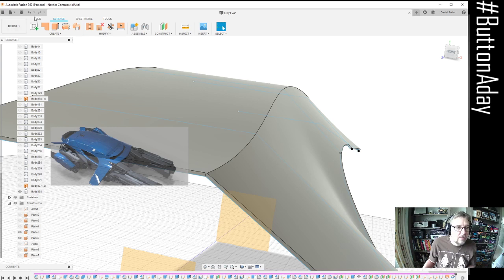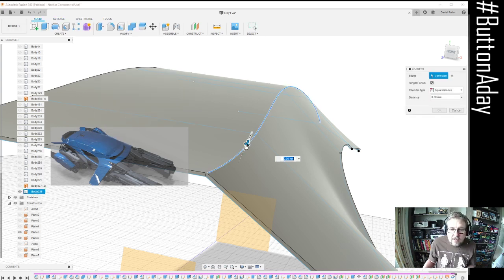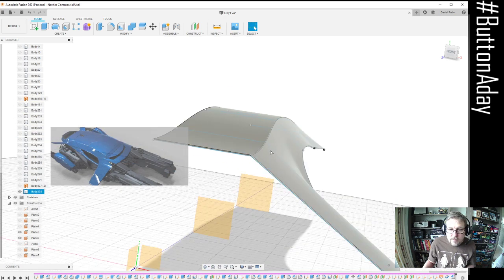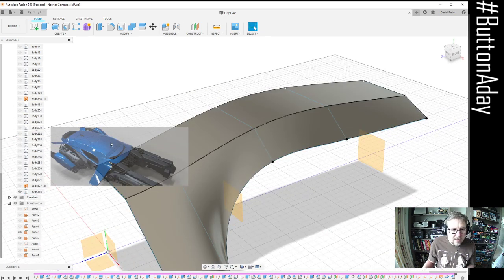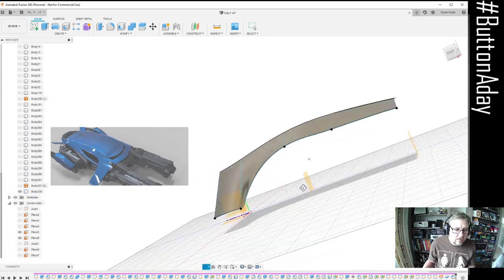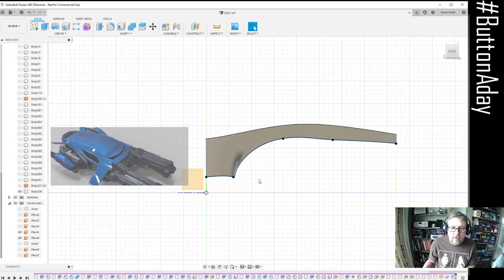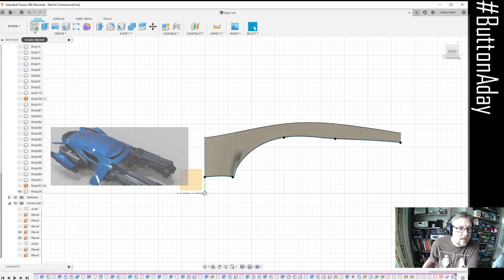We can go through back to our solids. We can add tiny details on here. We could add a little 3mm chamfer. Just again to that edge, just picks up the light. We get that sort of little reflection across there. And if we take on a side view, start a sketch.